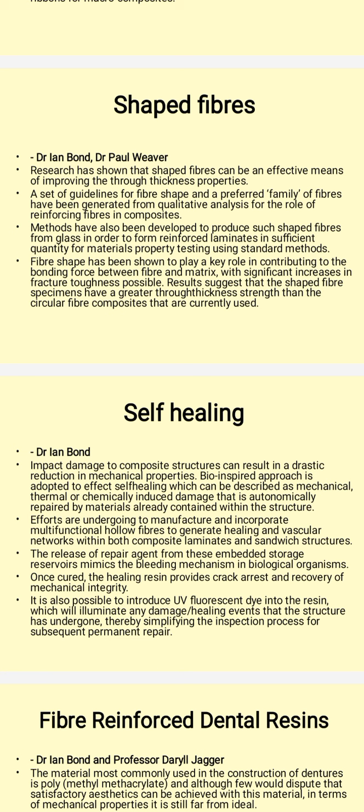It is possible to introduce UV fluorescent dye into the resin, which will highlight any damage or healing effects that the structure has undergone, thereby simplifying the inspection process for subsequent permanent repair.